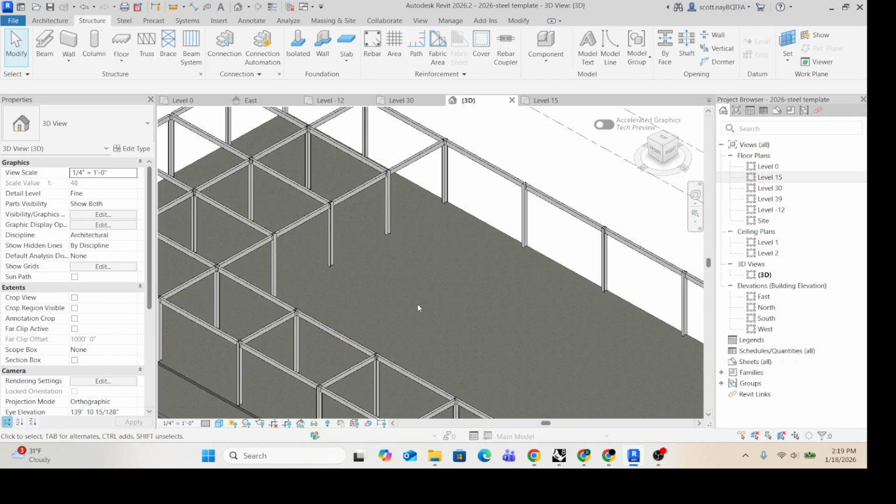Before I start copying though, I want to put some beam systems in between here. So if we tried to do a slab on here, the weight between the materials themselves and the occupants and everything else would be too much. So we need to again have some more steel beams that are even smaller than these 310s that run in between.